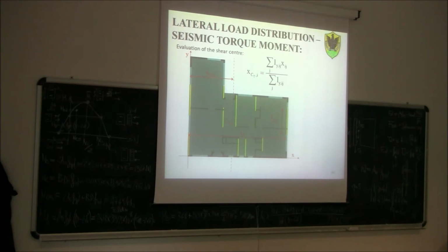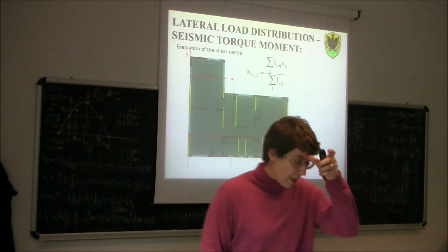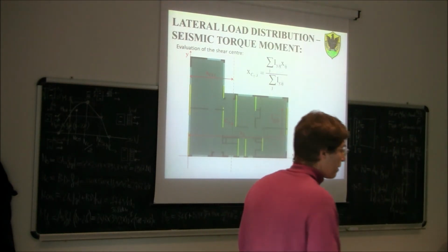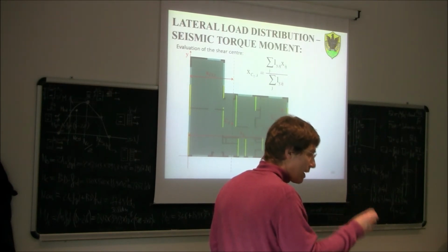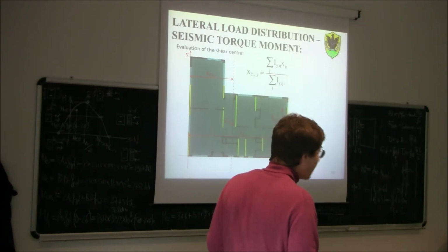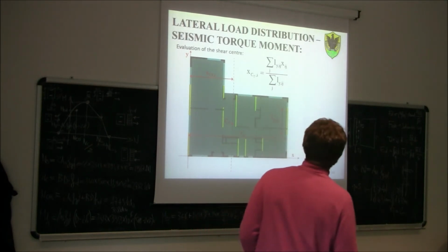Okay? So in other words, the center of stiffness can be regarded as the centroid of a system of masses where each mass is basically the length of a wall. Is this clear? Okay.